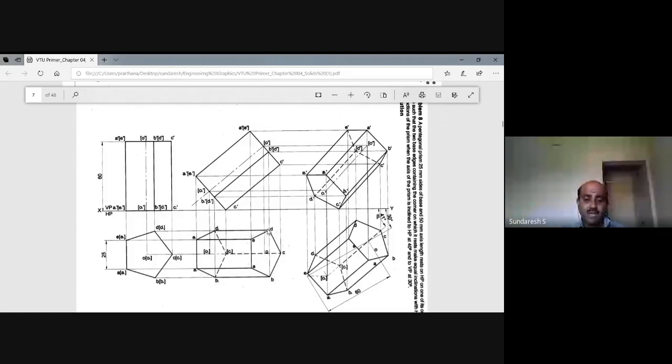Of course, this is completely visible. D1 is an outline, D1 E1 is an outline. Whether they are visible or not in the top view, you have to show them as a continuous line. Suppose A1, A, E, E1 is visible in the top view; that will form the complete rectangular face of visible edges. This is how you apply the rules of visibility for showing both visible and invisible edges. I hope you people are following.